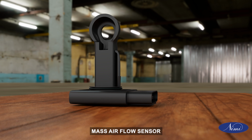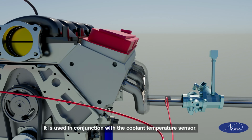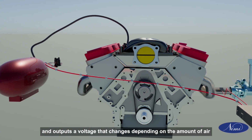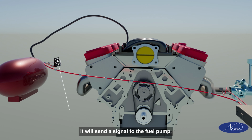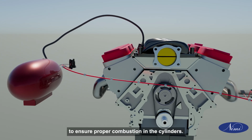Mass airflow sensor. The mass airflow sensor measures the air mass flow into the engine to determine how much fuel to inject. It is used in conjunction with the coolant temperature sensor and outputs a voltage that changes depending on the amount of air entering the engine. When more fuel is needed, it will send a signal to the fuel pump, which increases fuel volume to ensure proper combustion in the cylinders.